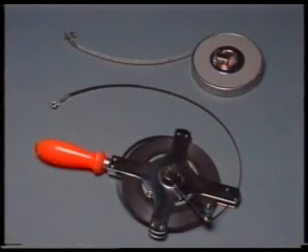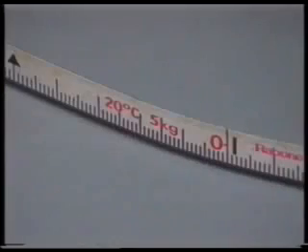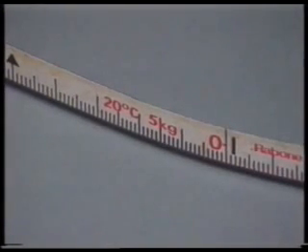If high accuracy is required, steel tapes should always be used, but they must be handled carefully since they will form kinks and can easily break if trodden on or if a vehicle runs over them. Steel tapes are normally graduated every millimeter, and they carry details of their standard temperature and tension. Be careful when taking measurements with them. The 0 point is not always right at the end of the tape.